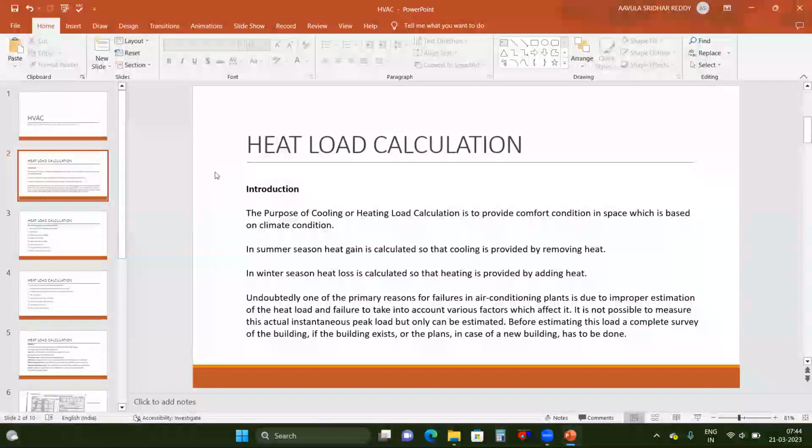So, for example, if you have designed an office space for 20 people, and the heat load you have considered is like 10 kilowatt or 5 kilowatt of electrical equipment, nothing but our laptops, printers, everything. So you have designed for 20 people and a 10 kilowatt equipment load. After that, there might be an increase of the load. So 20 people might become 25 or 30 also. In that case, this air conditioning equipment will not work properly. So that is a major thing.